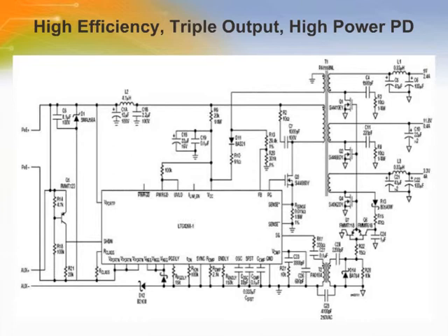Power sourcing equipment detection and power is passed through the data pair's high-power Ethernet transformer or directly to the spare pairs in the 2-pair 10/100BASE-T power over Ethernet system. The power sourcing equipment power is then controlled by the LTC4268-1 powered device and forwarded onto the switch regulator.